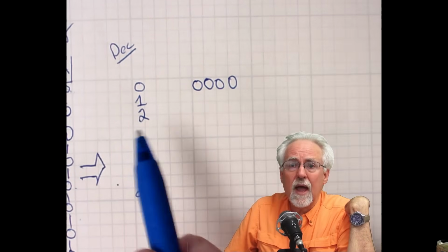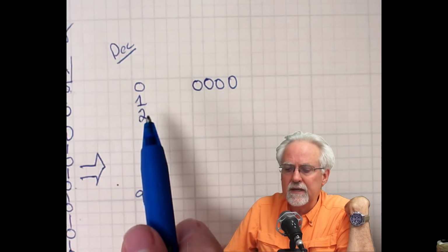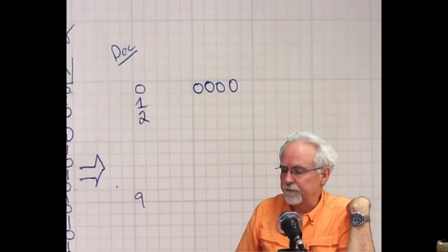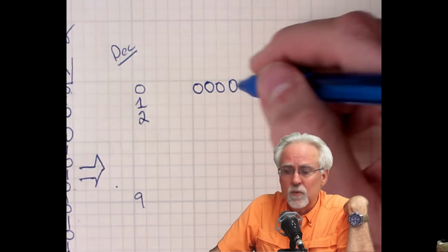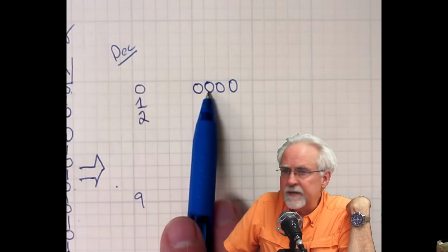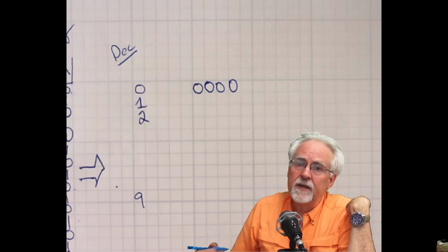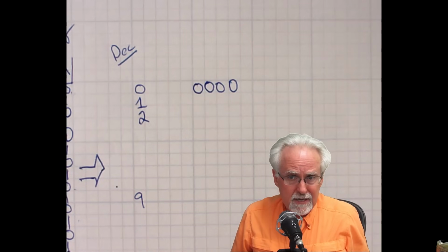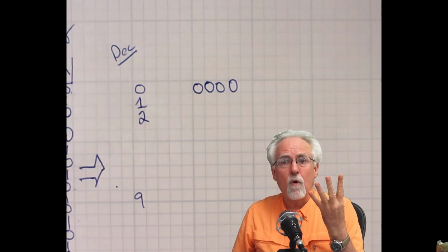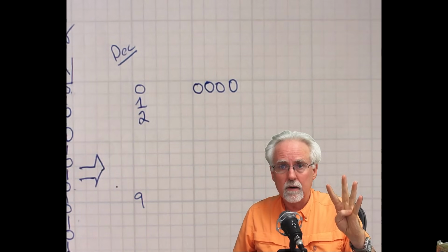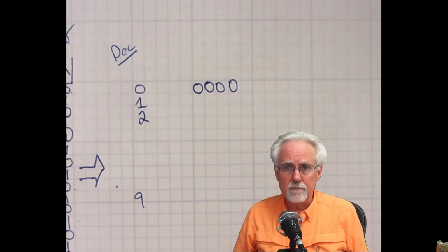All right. So how many pins will you have to connect those LEDs to on the Arduino? You'll have to connect to 4 pins. How many resistors will you need for this circuit? You will need 4 because each LED will need its own current limiting resistor. In your program, how many pin modes will you need? You'll need 4. Be sure and use variables because you are going to have 4 LEDs. You'll have 4 pins you're using. You'll have to do 4 pin modes.